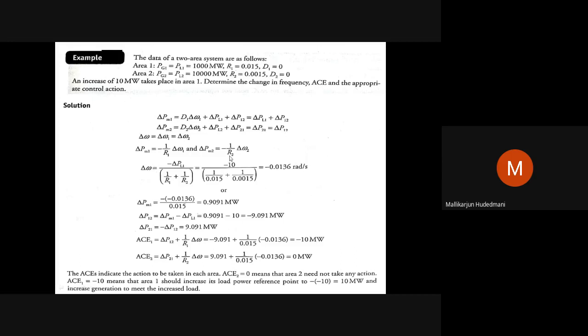Here, this looks like an old conventional problem. Earlier, we have seen such problems, but we haven't worked on the concept of ACE. We worked out what the frequency deviation is for such a shift in load, what the new frequency is, and what the share of generator 1 and generator 2 is. That was the area we worked. But in this problem, after having understood area frequency bias, we see how ACE becomes an important control parameter for interconnected operations with complete ALFC, with primary and secondary loops. Then we have to work very similarly, but view ACE at the final.